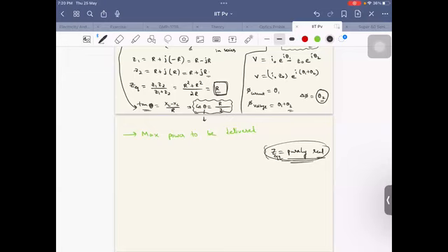So why that case? Because average power formula already we know. What is average power formula? VRMS into IRMS into cos phi. So there is nothing that you can do with VRMS and IRMS. These are fixed values based on the magnitudes of peak values of voltage and current. But which one can change, sir? This cos phi, which is our power factor, where phi is the power factor angle.